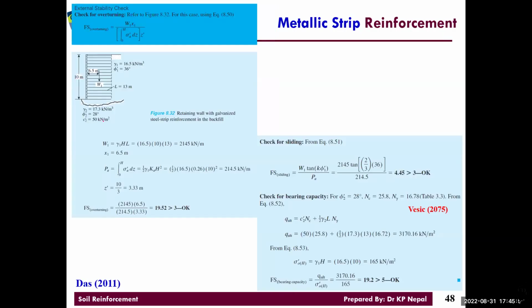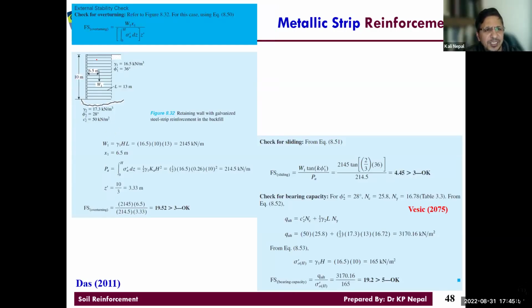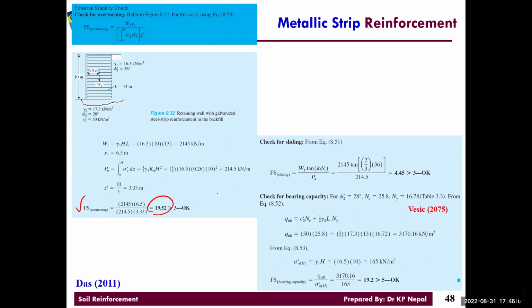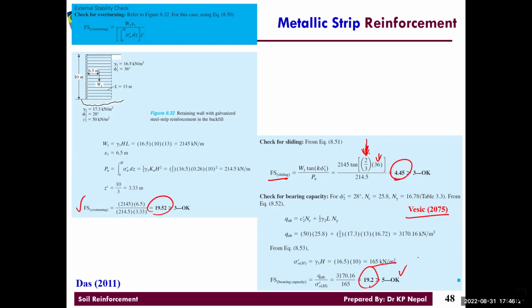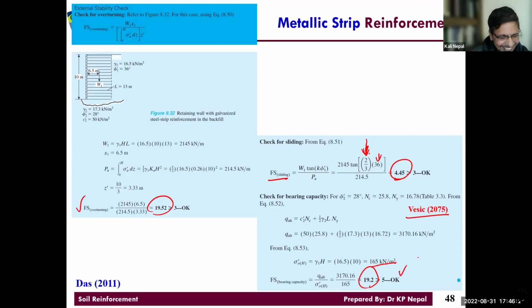Now, after that, then sliding, right? So let's start. So weight, we consider that. Overturning, can you check around 20? Yes, sir. Sliding around 4.5, yeah. That's 230. You see, that's the thing we need to be careful there. 2/3 of 36. Good. We use basic equation. 165 around 19.2. That's what we got for bearing capacity, yeah. Yes, sir. Same. You see, that easy, really.